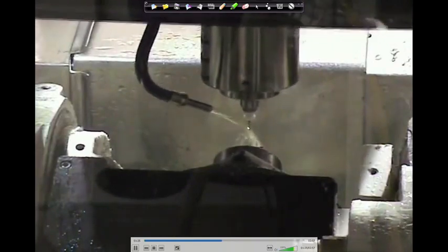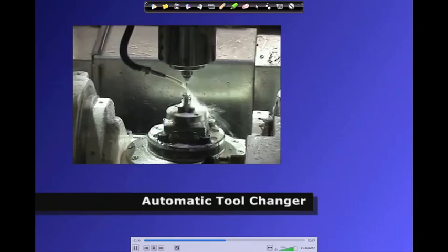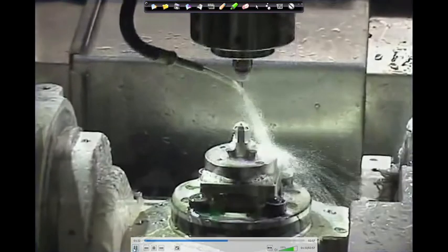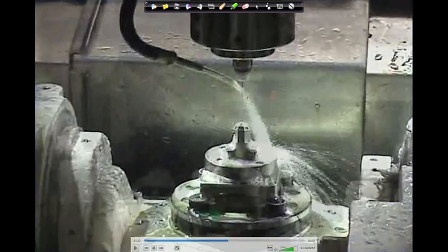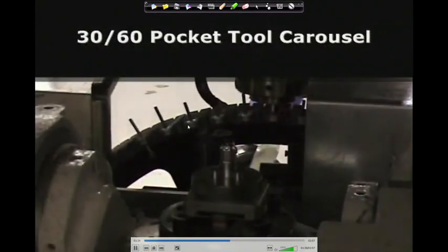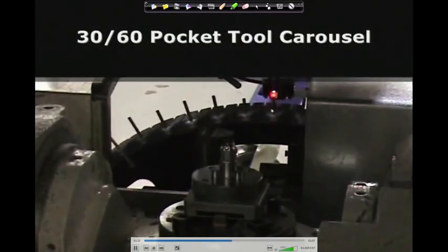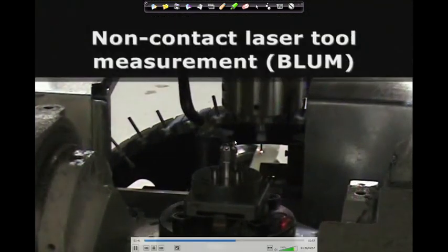And now, this is drilling from the top surface, and this is the automatic tool changer. You can change the tool also, because many times the same tool is not used for all the operations. Again, tool length compensation is a problem. Another tool may have a different length, so everything will be considered or calculated before it is mounted. Now, this is the automatic tool changer. The tool is moved from one location, another tool is picked up by the spindle, and then the operation is done.